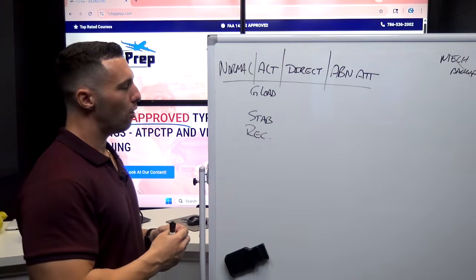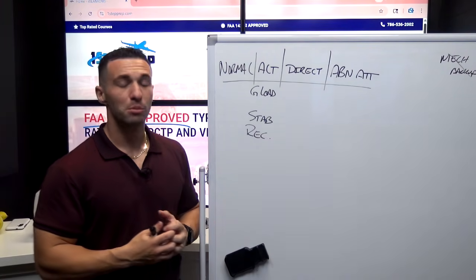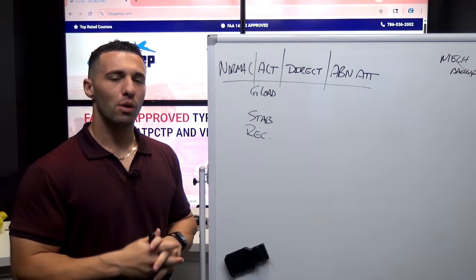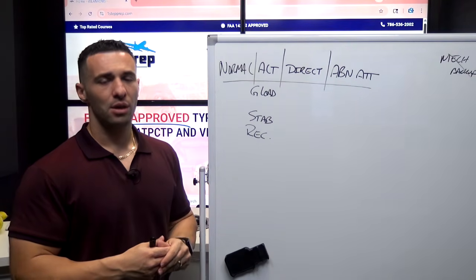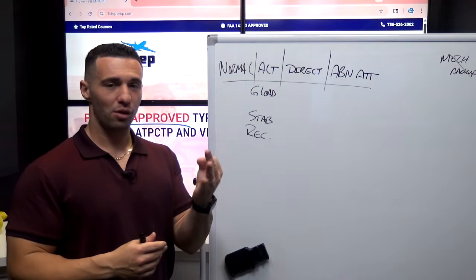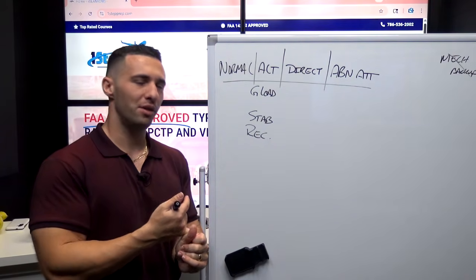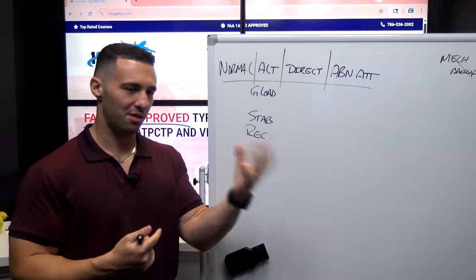Typically, when we are in sim training and checking, and we do our stall recovery, we want to recover at the first indication of a stall. We do a series of 3 stalls. The first one's with the autopilot on. Recovery is initiated at the autopilot disconnection. That's the signaling of alpha prot.